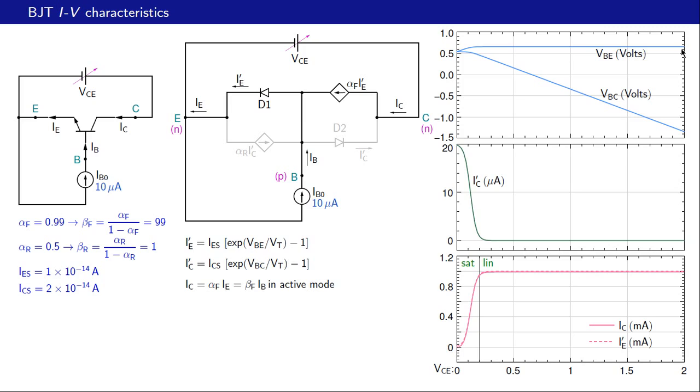And the entire difference, that is 2 volts minus 1 volt equal to 1 volt, has appeared in VBC. This was minus 0.3 volts and this is about minus 1.3 volts. So the base collector junction continues to be under reverse bias. The transistor continues to be in active mode. IC prime continues to be 0, and our collector current also remains equal to 1 milliamp.